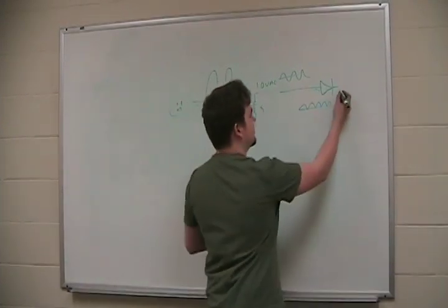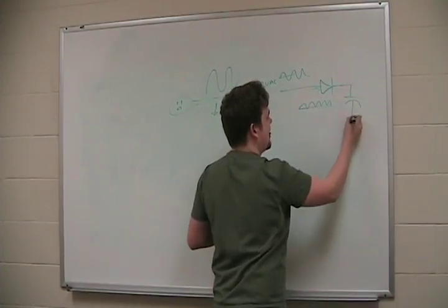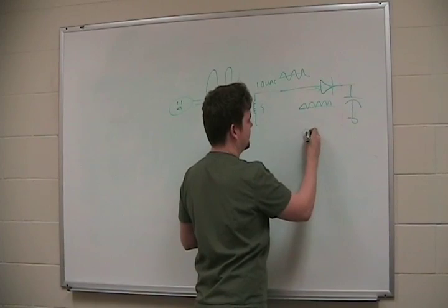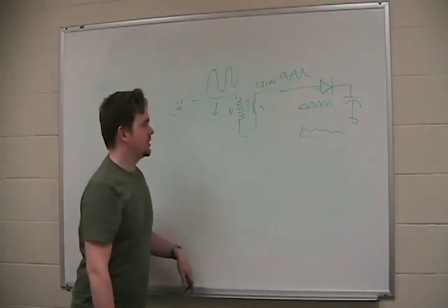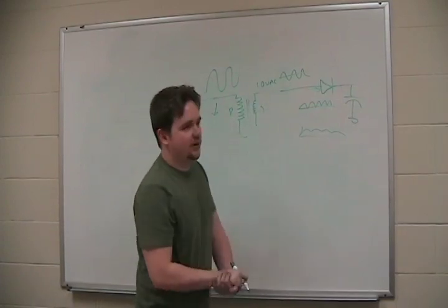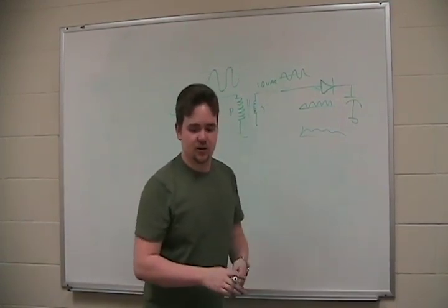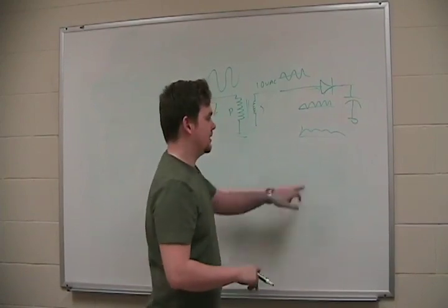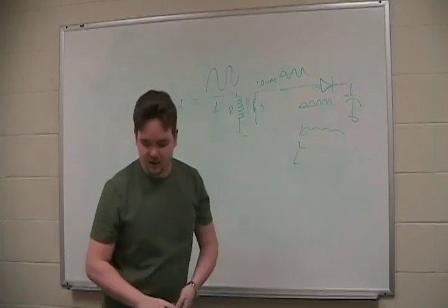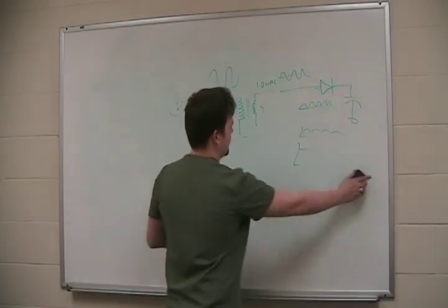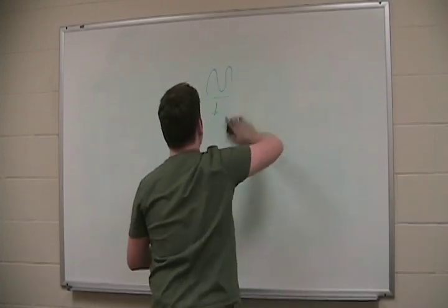And then, of course, like we talked about earlier with the capacitors, put a capacitor in there. We'll get a nice clean, not clean, but DC. So there's three different main kinds of rectifiers. There's half-wave, there's whole wave, there's bridge. Bridge being the most useful, the best. And you get the best output, the straightest output, especially when using a capacitor. Anyway, so that's another way we can use a diode.